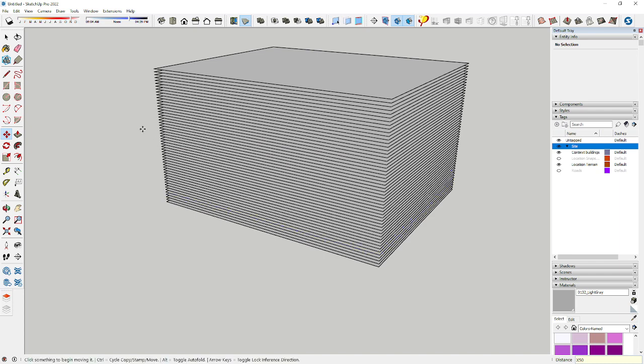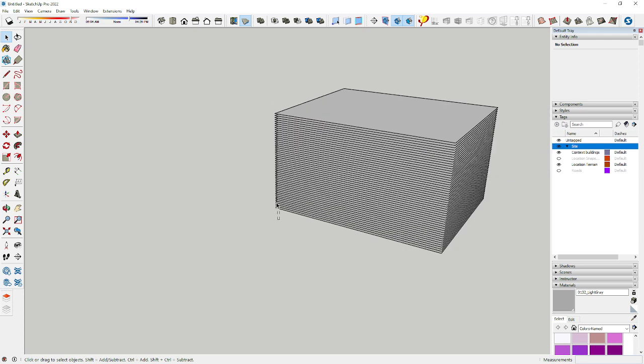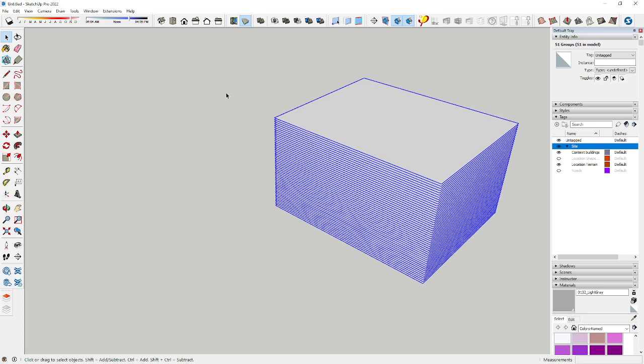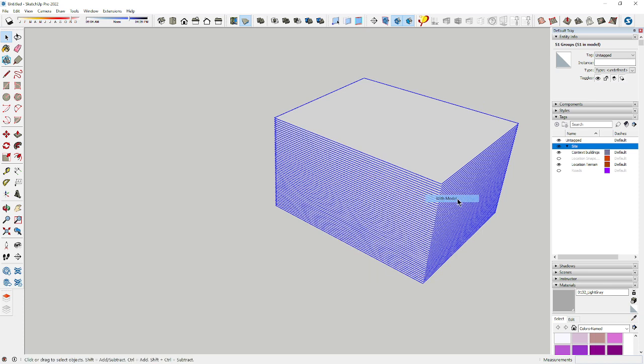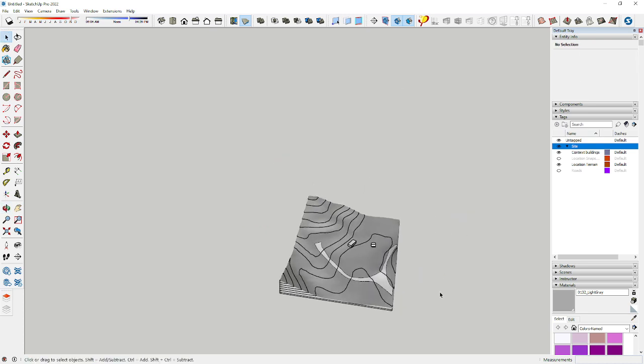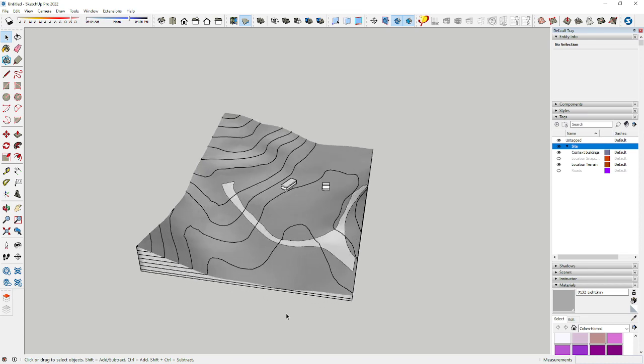So I've got all these planes, selecting them all. Now if I right click on that and I say intersect faces with model, and then I delete these, I now have contour lines on the model. And I might have wanted to go 5 feet or something different, but...